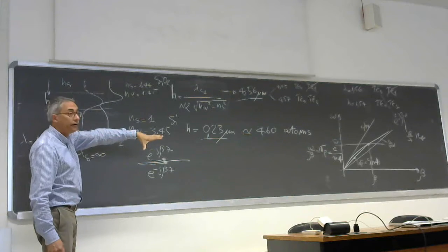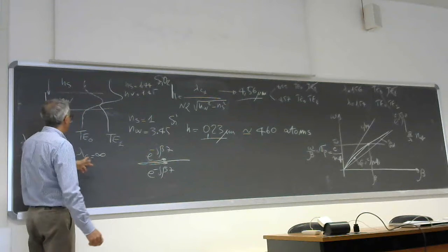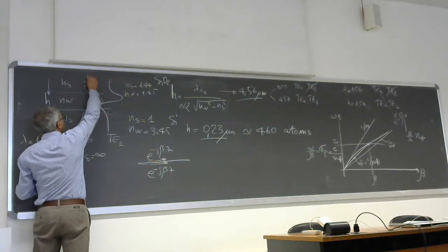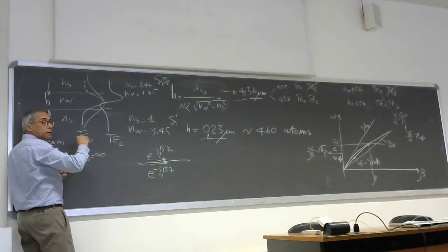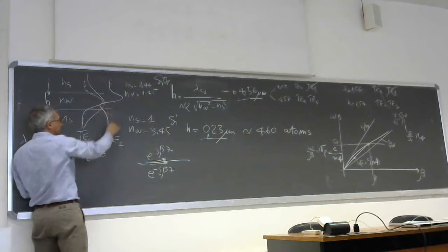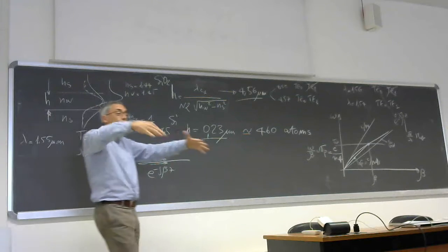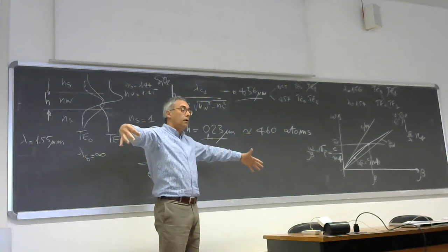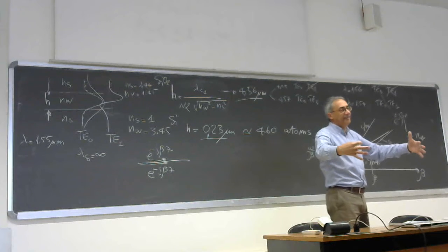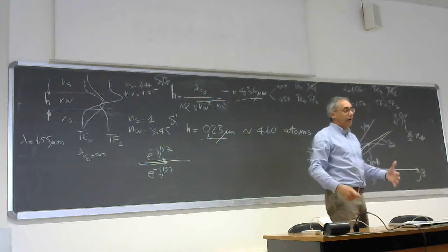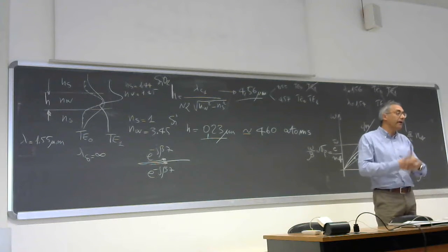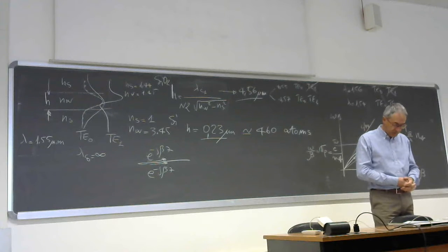If you decrease the frequency, so increase the wavelength, you have a broader mode, and if you keep decreasing, you get something huge compared to the core. In practice it is no longer guided, but from a theoretical point of view it is guided. The solution exists.